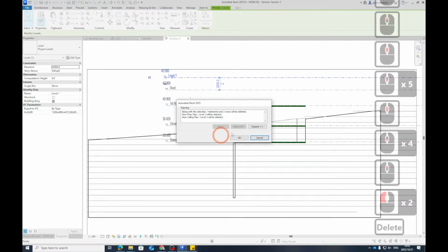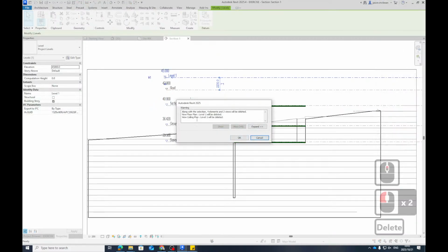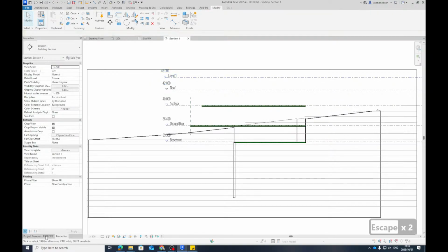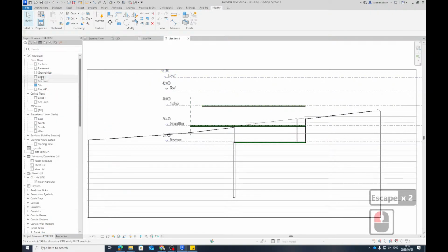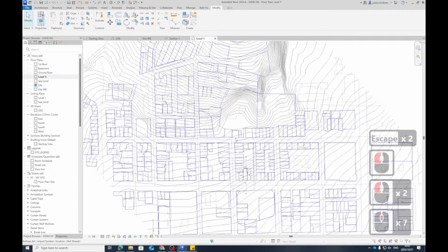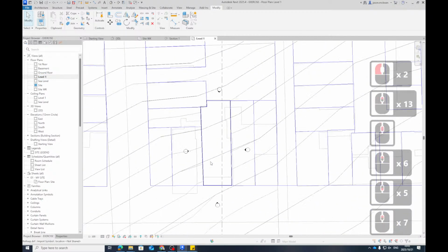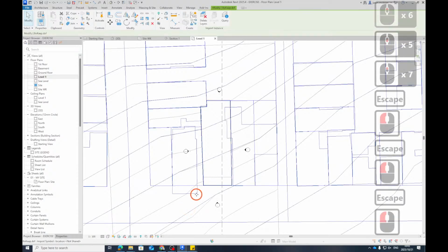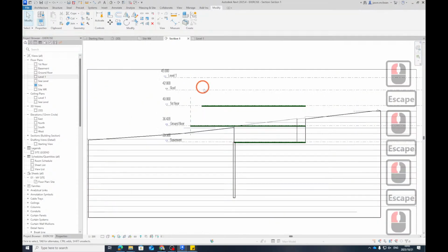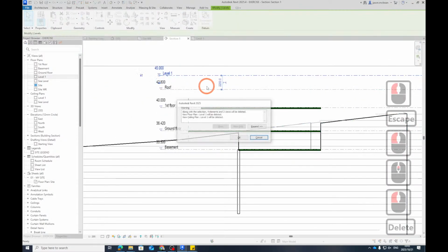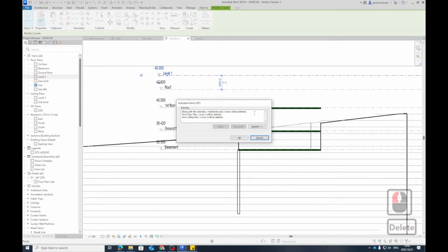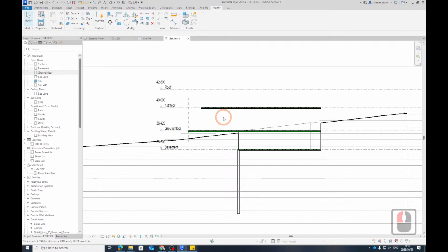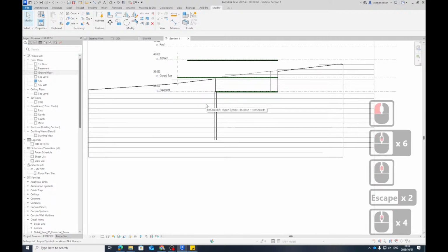This one we can also delete. Okay, there's some other elements linked to it, so I might leave it for now, but you can move them. So if I go to level 1, this is the only thing, ArchiCAD, Revit, same problem. Some of these objects or some of these elements here might be associated to that level 1, so we just need to make sure. But you know what, this is easy to bring back, so I'm going to remove this for now. So it's telling me view plan, ceiling plan, and 4 elements. Okay. So not much was deleted.